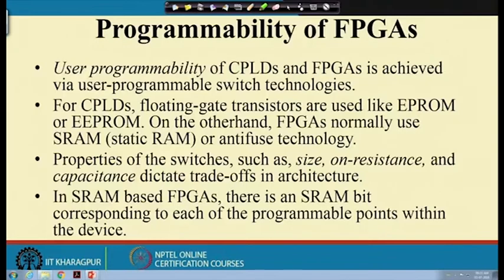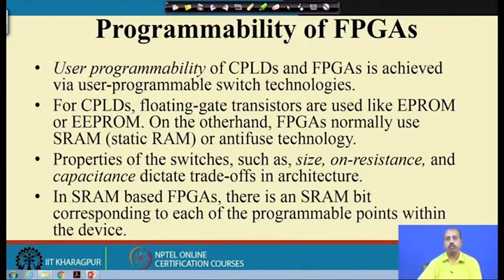Their size will determine the amount of logic that you can put there. On resistance will determine the delay in the communication. So, on resistance and capacitance will dictate the delay that you will have in the design.